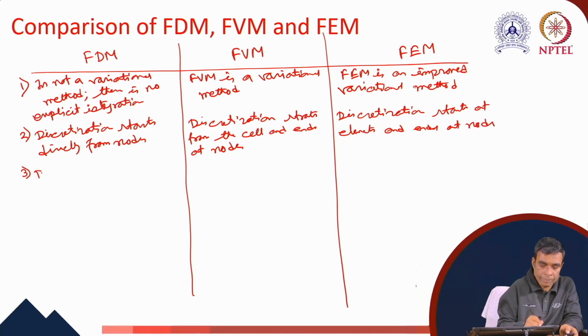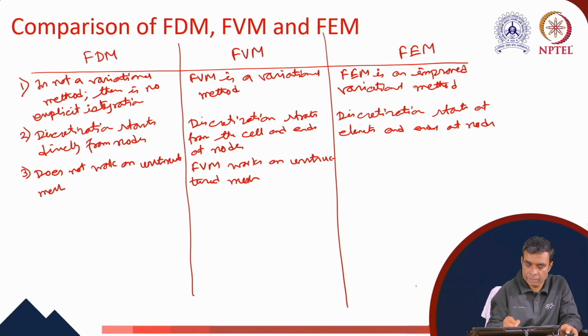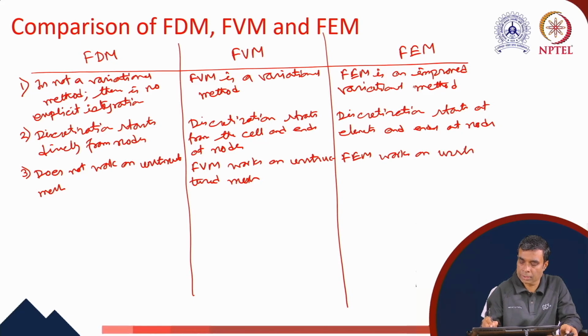FDM does not work on unstructured mesh. FVM works on unstructured mesh. FEM certainly works on unstructured mesh.